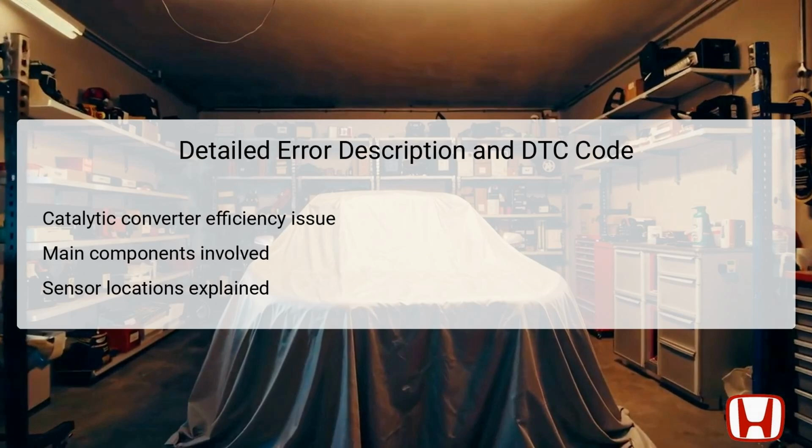DTC P0420 points to an issue with the efficiency of the catalytic converter, a critical component of the exhaust system. The catalytic converter operates by converting harmful exhaust emissions into less harmful gases. Surrounding this converter are the oxygen sensors: the primary, or upstream sensor, HO2S1, which monitors the oxygen content prior to the converter, and the secondary, or downstream sensor, HO2S2, which gauges the output after the exhaust has passed through the catalyst.